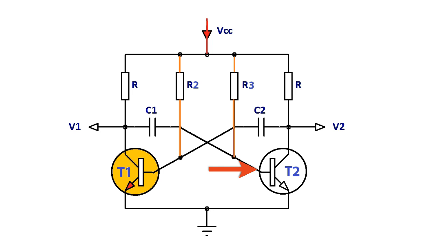Transistor TR2 is driven into cutoff, so capacitor C1 now begins to charge in the opposite direction via resistor R3, which is also connected to the positive 6 volt supply rail, VCC. Thus the base of transistor TR2 is now moving upwards in a positive direction towards VCC with a time constant equal to the C1 x R3 combination. However, it never reaches the value of VCC, because as soon as it gets to 0.6 volts positive, transistor TR2 turns fully on into saturation.